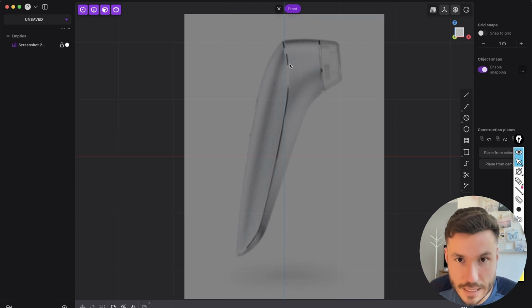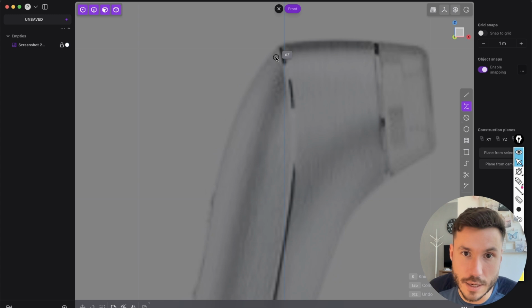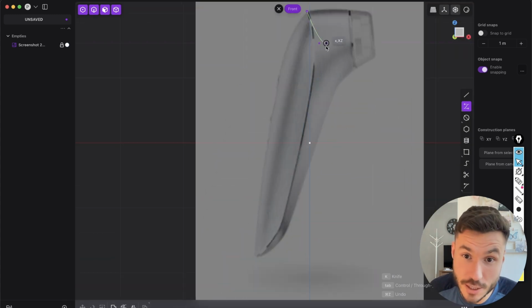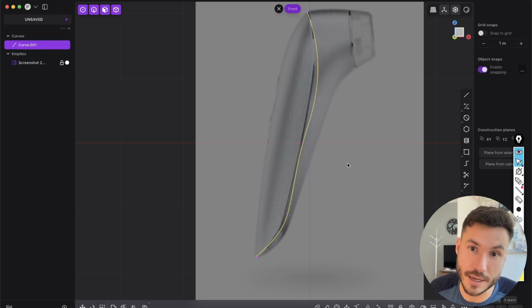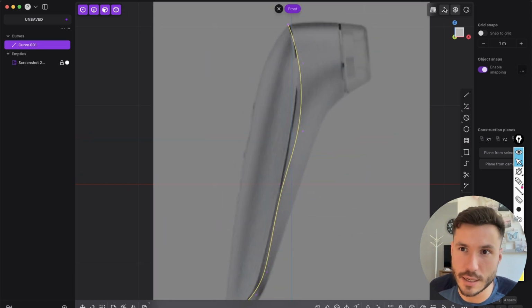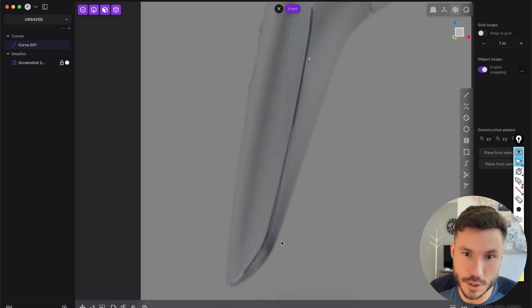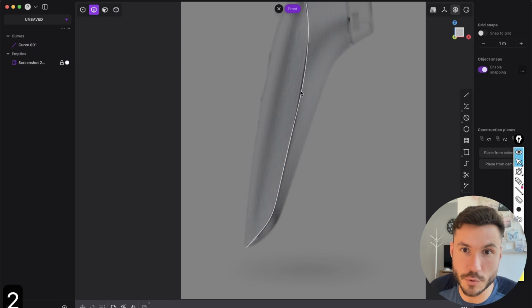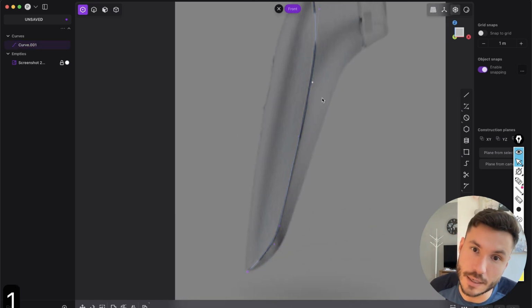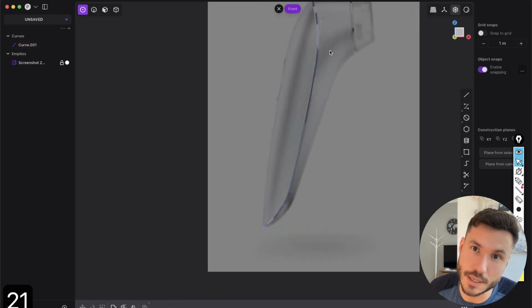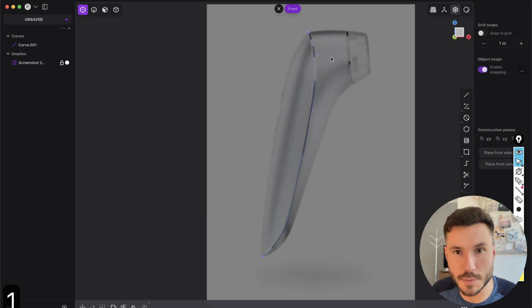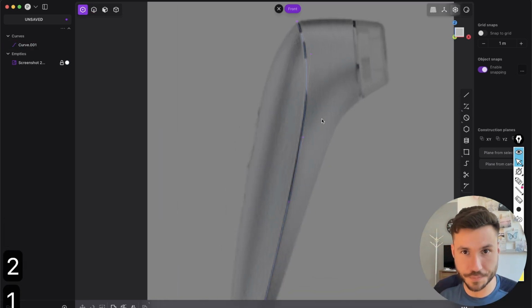So first of all, we create a control point curve, and we just go from this point and just follow this beautiful edge here. Something like that. Doesn't matter how you create the points. Let me hide this grid, because now you can adjust those points here one by one. And that looks beautiful, right? So here we have the curve. And yeah, I'm just rushing a little bit here in this quick tutorial, but you just spend a little bit more time and love with that.